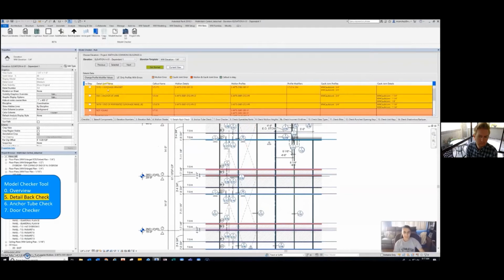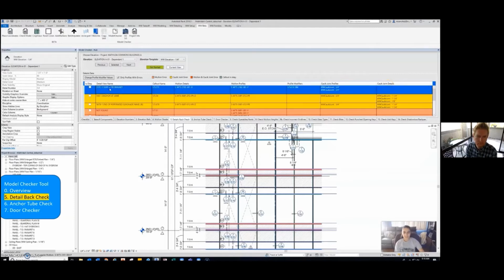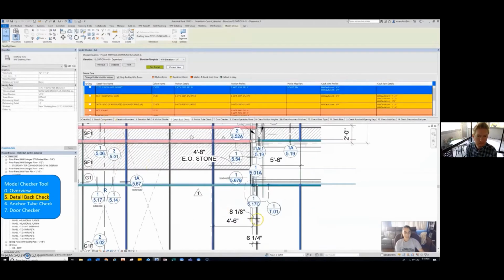So right away, this first issue, since it's highlighted in yellow, we know that our issue is in the joint that we have. So the joints, probably from the detail and the mullion, are not matching. Jump here where it says joints, and you can see that inside the model in the profiles we have 3/4 inch joints, whereas in the details there are no joints. Simply double click and it's going to take you right to where this issue is happening.